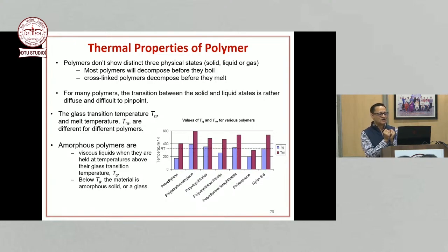Tg is the temperature below which, and below means you are cooling it, your material becomes less easily flexible. The chains are becoming more rigid. So let's say you have a polymer at a certain temperature, you start cooling it,